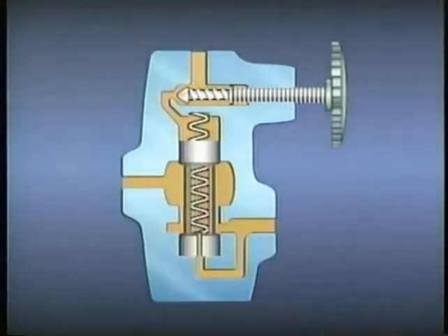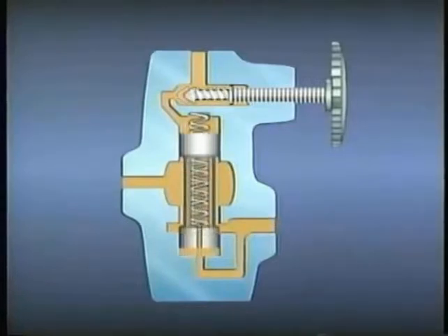At the same time, fluid flow through the orifice creates a pressure difference that causes the spool to move upwards. As the spool moves upward, it partially closes the outlet. This action, along with draining off a portion of the fluid through the pilot valve, effectively reduces the pressure of fluid leaving through the outlet to the other part of the system requiring lower operating pressure.